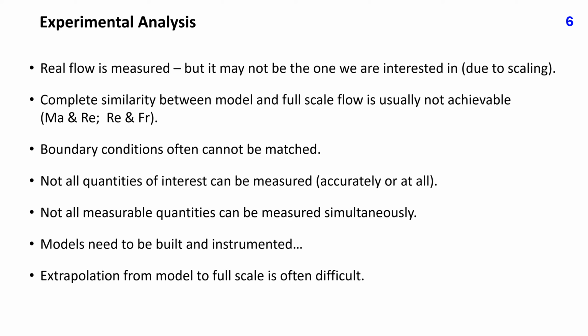Accurate velocity measurements, for example with laser Doppler velocimetry, can only be done pointwise, which takes time and requires ensuring that the flow does not change in the meantime, that is, keeping the temperature and boundary conditions the same all the time. Building the models, instrumenting them, and running the experiment is time-consuming and costly.